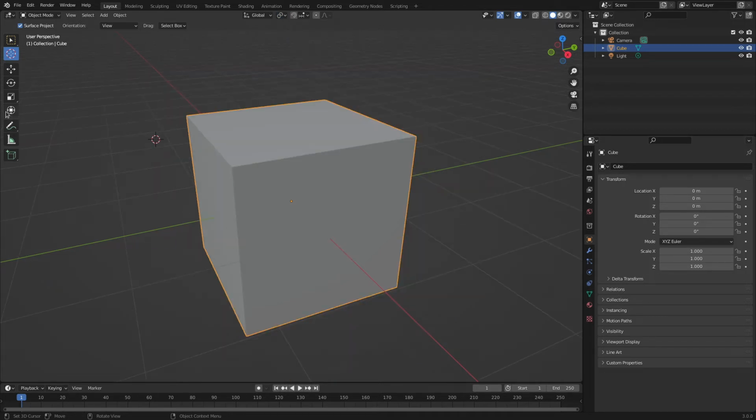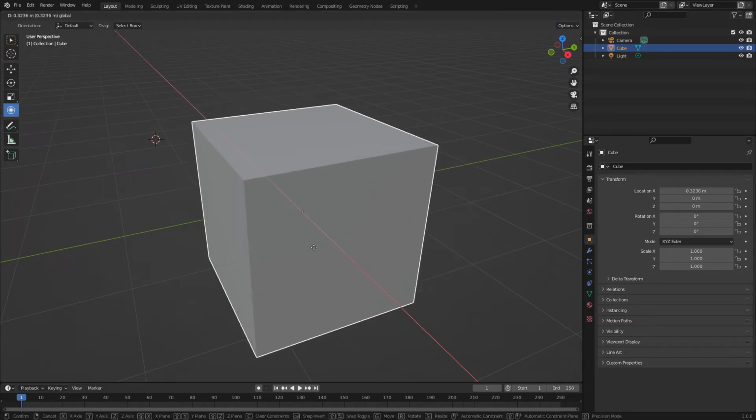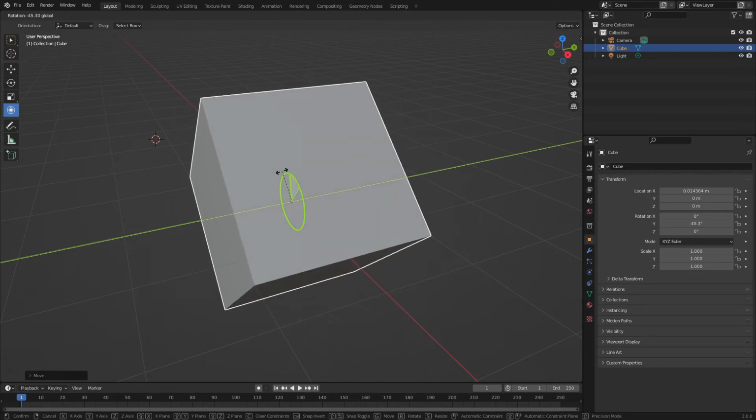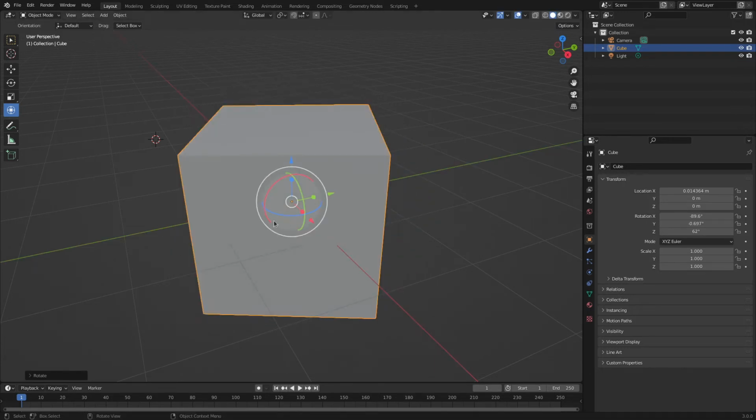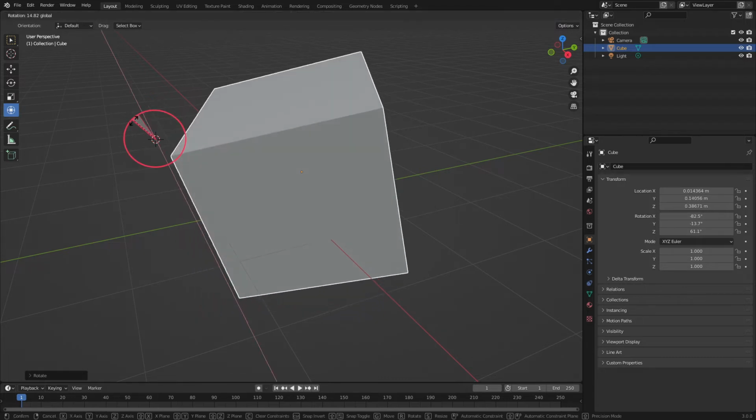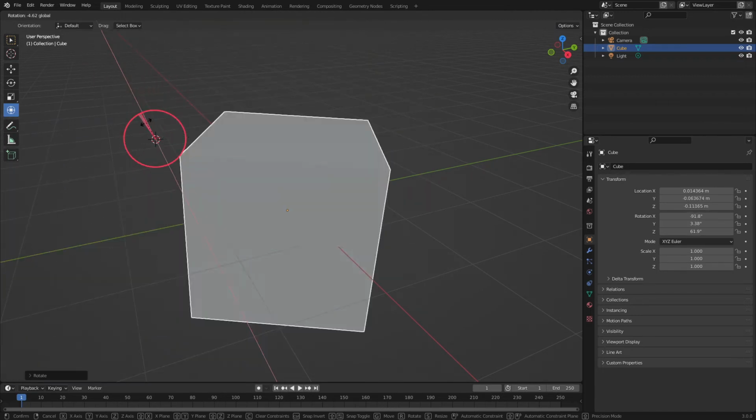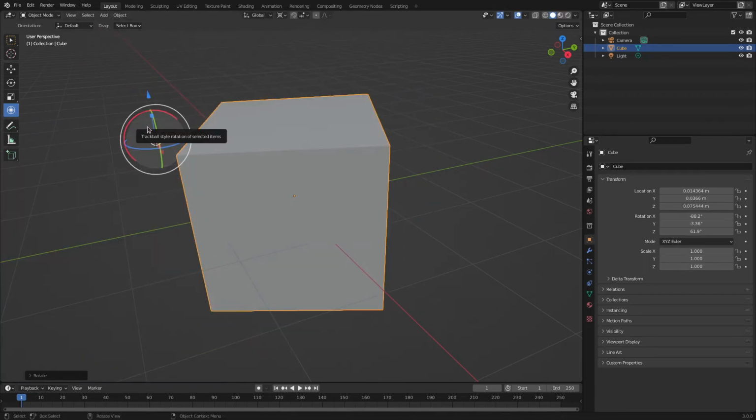And I'll select my transform gizmo. You'll notice that it is completely oriented around the little orange dot. That is my pivot point. See it? Anything that I do is done around that pivot point. So that's what your pivot point is. For instance, if I switch it to 3D cursor, and again we're going to go over this in much more detail, it has now oriented around the 3D cursor, and if I move this, now the 3D cursor is the pivot point. So hopefully that makes a little bit more sense what that is.